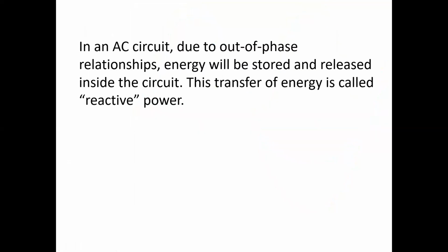Now, this is a little bit different when we start getting into out-of-phase relationships. In an AC circuit, due to these out-of-phase relationships, energy will be both stored and released inside the circuit. And this transfer of energy is called reactive power. And the interesting thing about this type of power in an AC circuit is that it's not lost to the circuit. It's stored in the circuit, and then it's released back to the circuit.